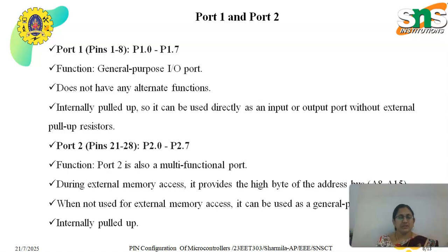Port 2 pins are 21 to 28, P2.0 to P2.7. This port also acts as a multifunctional port. During external memory access, it provides the high byte of the address bus, that is A8 to A15, and when not used for external memory access, it can be used as a general purpose input output port.